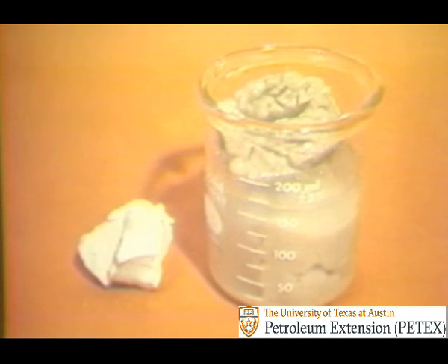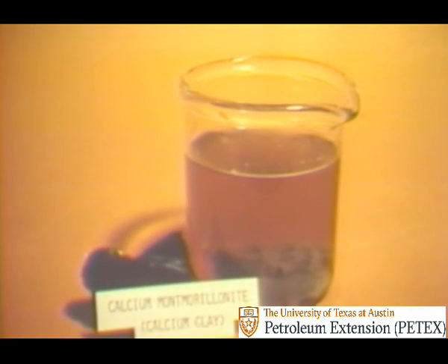Here's what we actually see. At left is a piece of sodium clay, crude bentonite. The beaker at right shows what happens when the clay is put in water. The clay hydrates. It takes on, or absorbs, so much water it expands to about 8 times its original size. This means that viscosity is very high. On the other hand, if the clay is calcium clay, calcium montmorillonite, hydration is not as great. Calcium clay only swells about 2 or 3 times its original size. Therefore, calcium clay does not give as much viscosity as sodium clay.